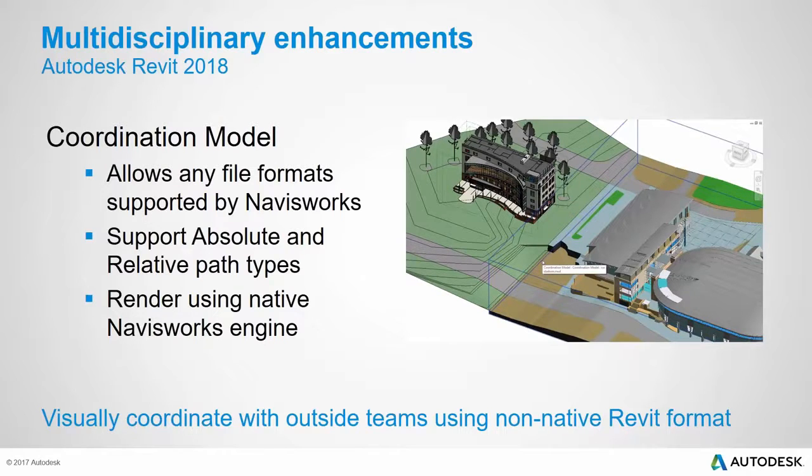They also leverage the shared coordinate processes. So as long as the Navisworks model is assembled correctly, you should be able to bring that directly into Revit, leverage the shared coordinates, get the models to line up, and then also run collisions inside of Revit directly, and get nice sliced views of models.